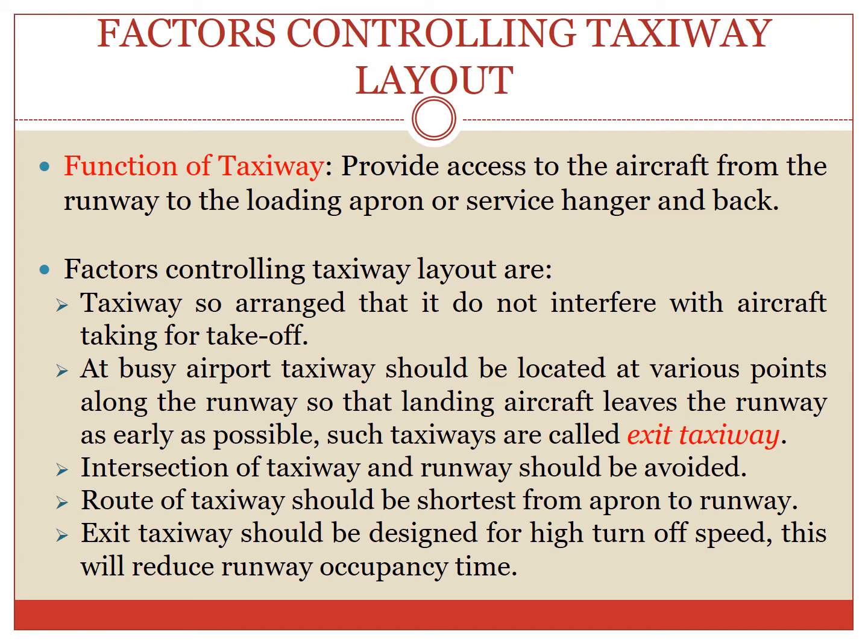This is for the security of the taxiing aeroplane from sabotage. All the sections of the taxiway system should be visible from the aircraft control tower. Lastly, the taxiway layout should be planned to avoid interference with navigational aids by taxiing aeroplanes or ground vehicles using the taxiway.